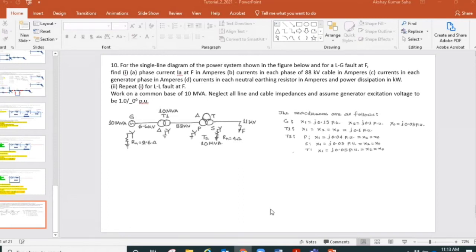So the third harmonic component will cause a third harmonic current flowing in the circuit. For that, we will have to provide a path for the third harmonic current to flow, so that when it flows, it doesn't cause other problems, like overheating and many other problems. We can discuss that in another session. So we must have the delta connection for providing a path for the third harmonic current to flow. That's why we put the other winding in delta.